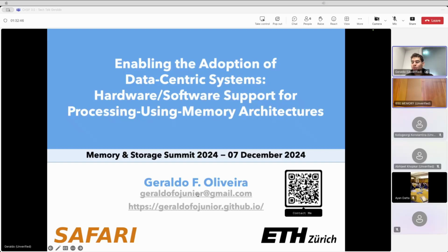So usually, when you're designing a processing-in-memory chip, you take that restrictive power budget of the memory chip itself into account. Because of that, the gate itself is more power efficient compared to a CMOS-based or processor-centric approach. So I don't know if I fully answered the question.